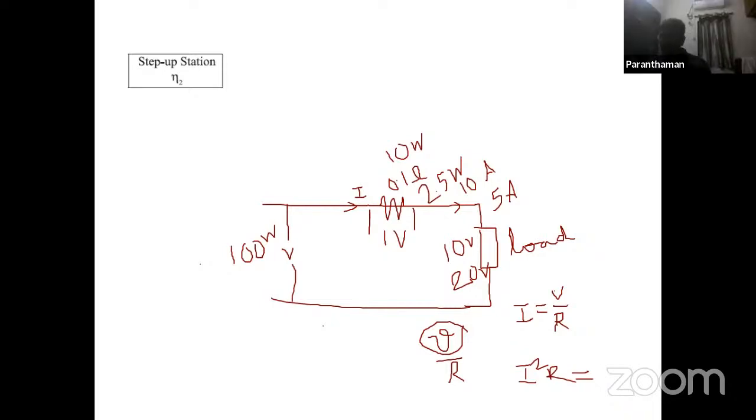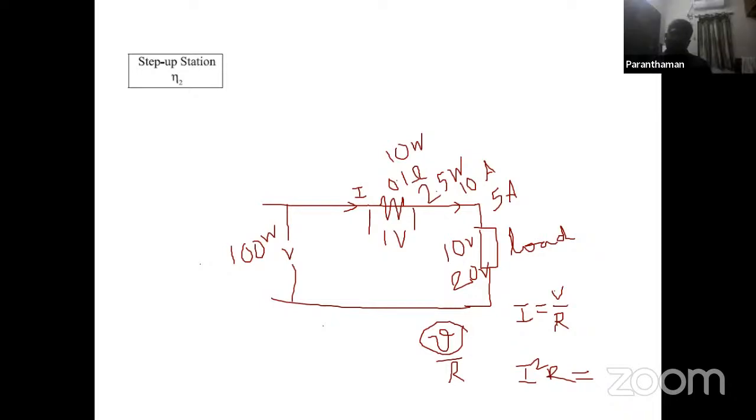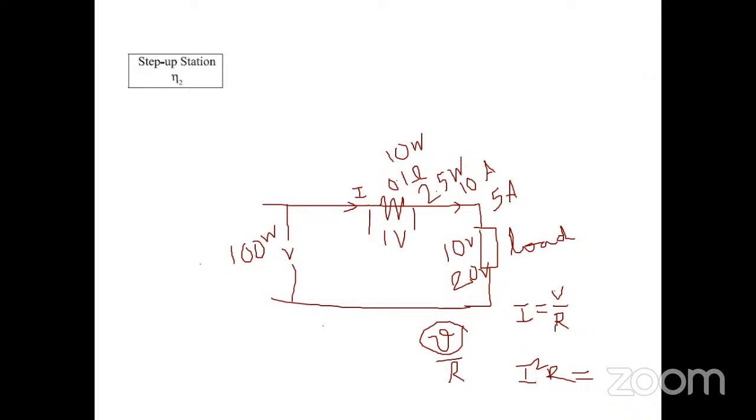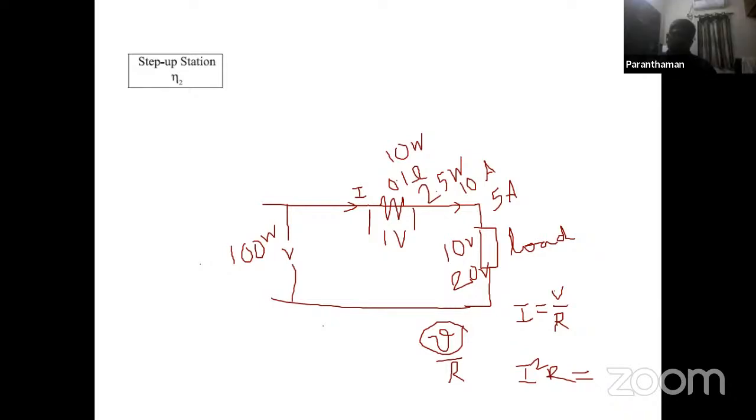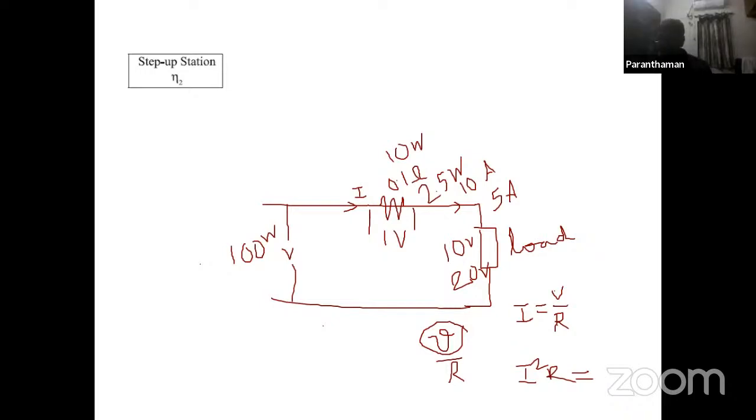So, sir, you just type 0.995 in the calculator. What is the second, sir? The 400 kV transmission is the highest voltage, so it will have the lowest transmission loss, nearly 1%. That is 99%. You have to multiply it with the previous one with 0.99. So 0.995 into 0.995 into 0.99. This is the 400 kV transmission.